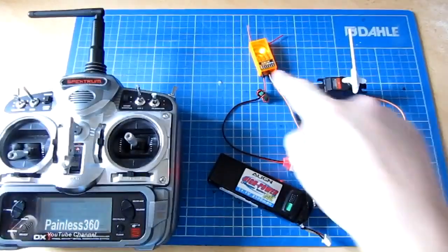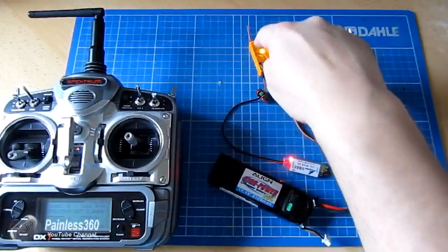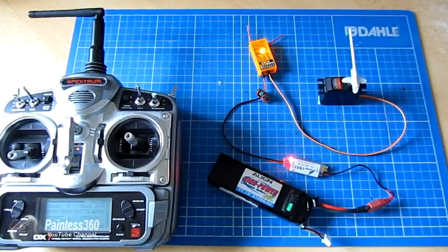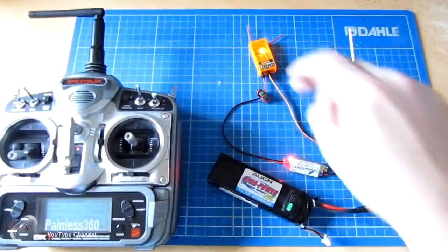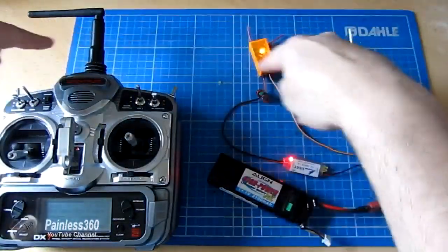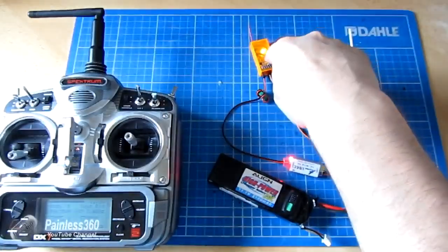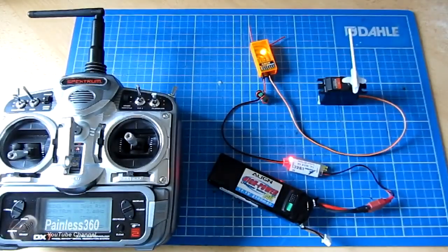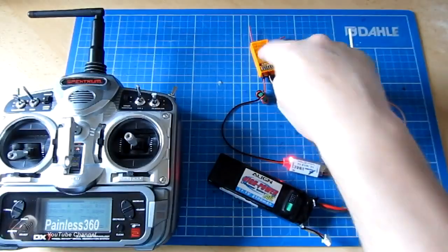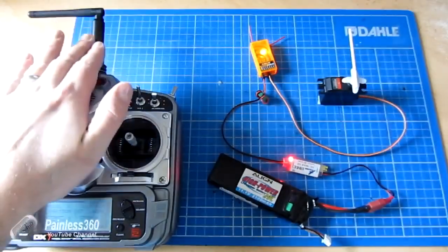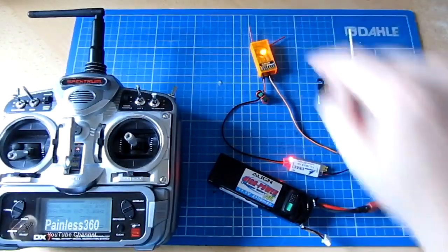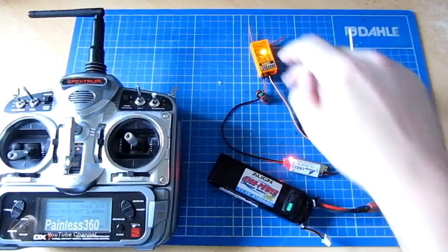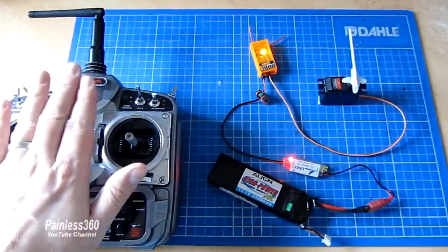A lot of the systems use 2.4 gigahertz to talk between these two parts, but actually are using a different language. So it's like if you imagined that this radio is speaking English and this radio is speaking English, they understand each other. If this was a Futaba receiver, you could say for example, was speaking Spanish and this radio was speaking English. So in that case, even though the radio was transmitting at the right frequency, the receiver wouldn't understand what it was saying. So you have to make sure that the receiver is going to work with your radio.